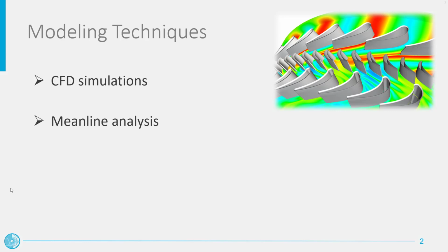Turbo machine characteristics are instead taken into account in system simulation by using maps, which describe how the characteristic parameters of a machine, like isentropic efficiency, mass flow rate, or pressure ratio, vary over its operating envelope. This approach enables very fast computations, theoretically guaranteeing at the same time high accuracy.